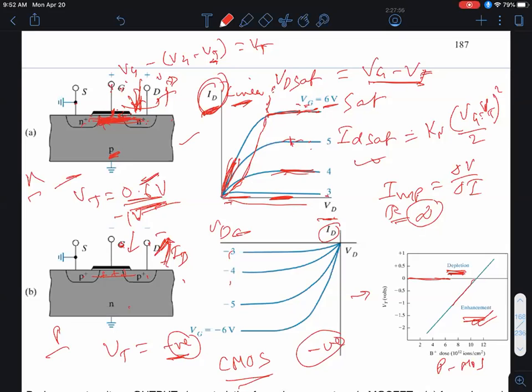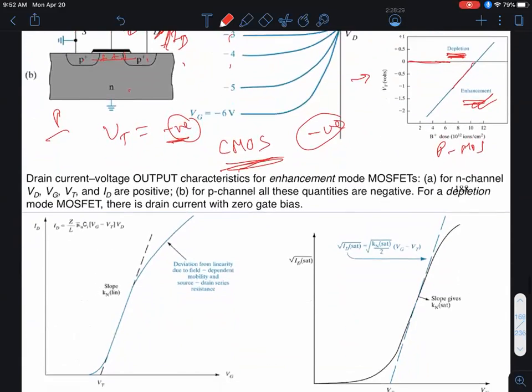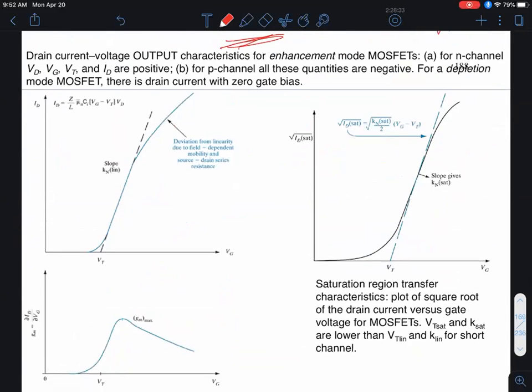Okay. Now, because one of these two transistors is always in the off state, CMOS consumes very, very low levels of power. Okay. And that's really behind the fact that you can integrate literally billions of these transistors in your computer microprocessor chips or your cell phones and things like that, because it consumes such low power. That's especially important for mobile applications, like in your cell phones. Otherwise, your battery would run out in maybe a few minutes instead of lasting a day. Okay, we'll talk about that probably next week. Any questions?